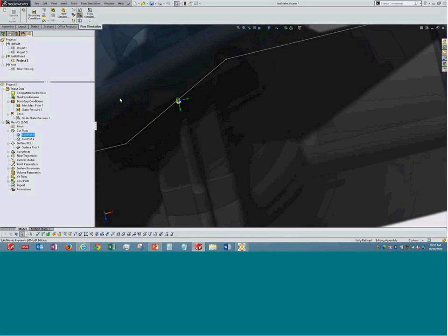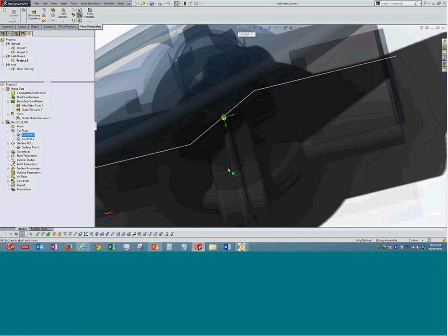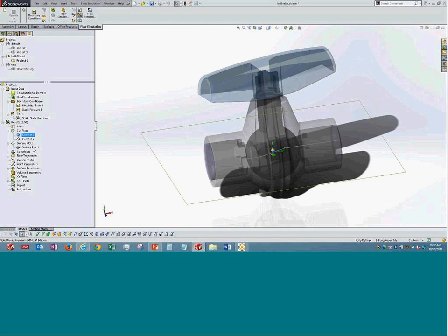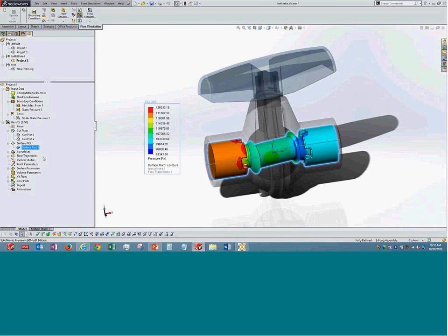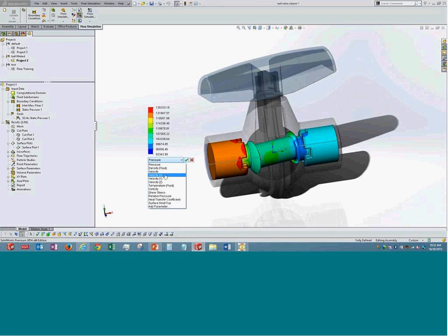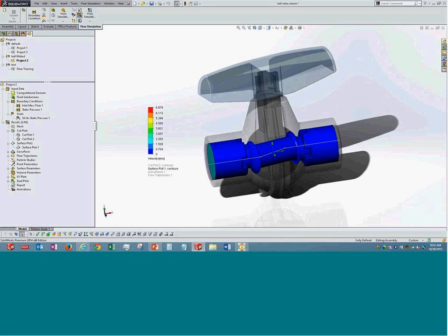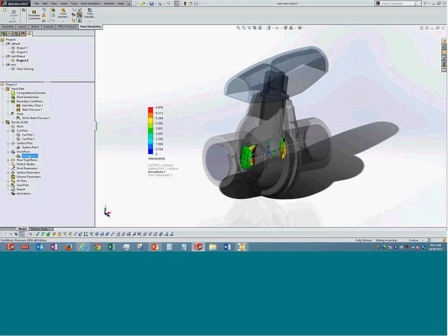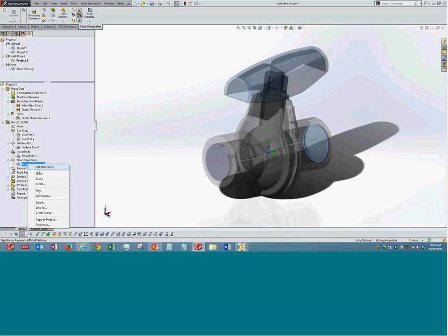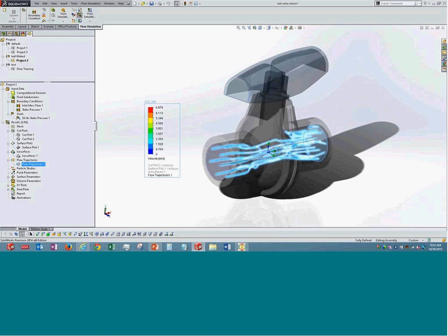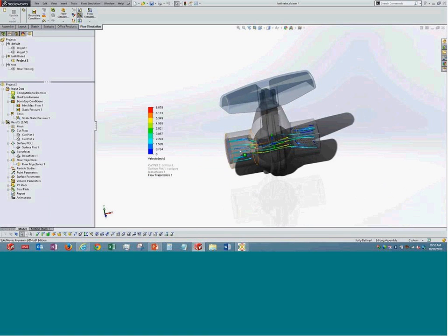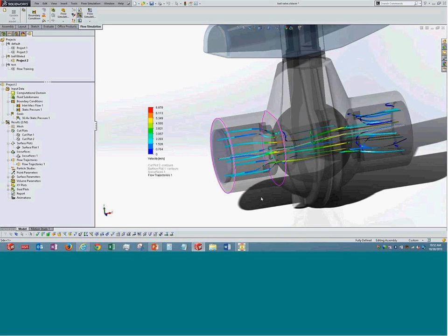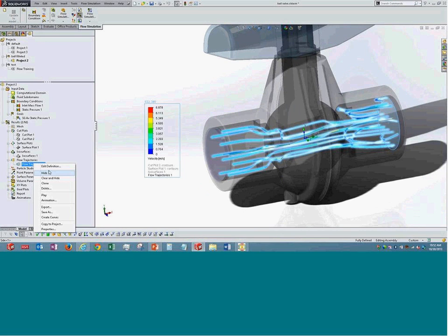So specify the inlet or the location from which you want to see, and the number of trajectories that you want to see. On that, the software can show us how the fluid is going to flow inside the system. Over here, I'm going to animate it at the moment and see how it goes. You can see a few lines which are coming from the outlet, which is nothing but the reverse flow that might be happening. With the initial pressure conditions, the flow actually coming in even from the outlet oscillates and goes back.